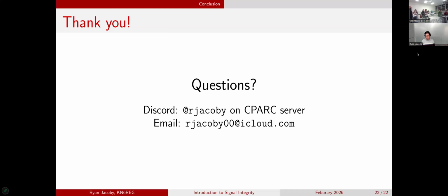For the decoupling capacitor, when you say put it close to your device, what does that mean? Just packed together? Yeah, as close as you possibly can, right next to it. Sometimes it's pretty common on really dense boards to put them on the other side, directly below the part they're decoupling. Especially for BGA packages, you're already having one via for every ball, especially all the balls in the middle of the package. A lot of those are going to be power supply pins, and you can just drop capacitors directly on the backside of those vias.